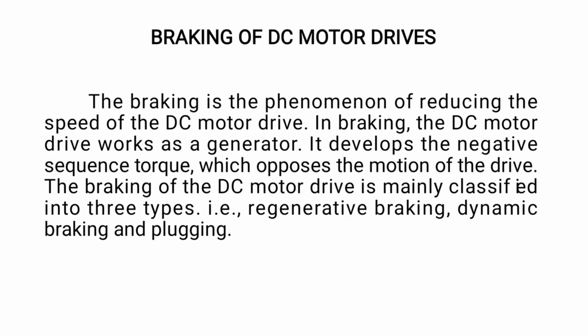Braking of DC motor drives. Braking is a phenomenon of reducing the speed of a DC motor drive. In braking, the DC motor drive works as a generator. It develops a negative torque which opposes the motion of the drive. The braking of a DC motor drive is mainly classified into three types, that is regenerative braking, dynamic braking and plugging.